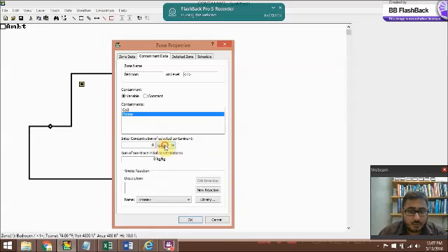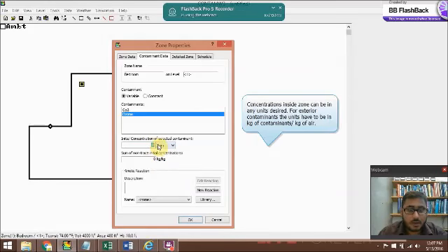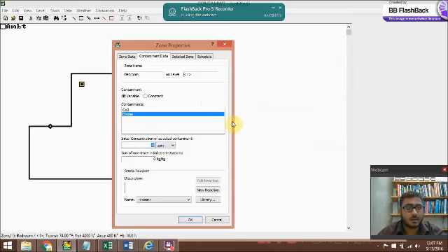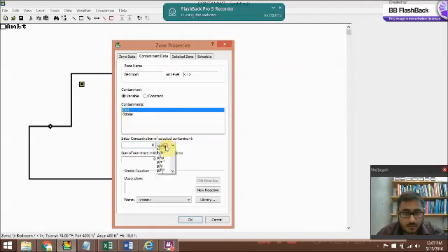In this case, you can set up the values in ppm, but I'll explain later how you can set up the ambient concentrations, and that has to be determined in the kilogram of the species divided by the kilogram of air units. So let's say for CO2 we have 400.